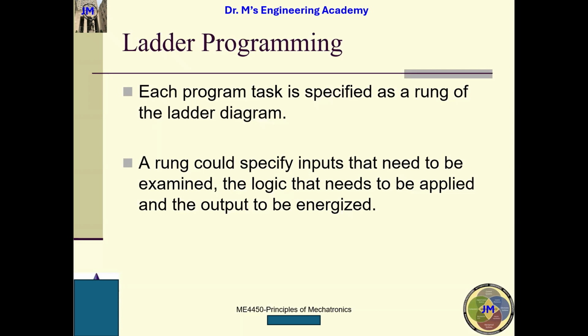So the system runs the program from the top to the bottom and from the left to the right. Top to the bottom, left to the right. If any rung does not have any output, you can simply delete this rung. Why? Because this rung does not do anything for you.